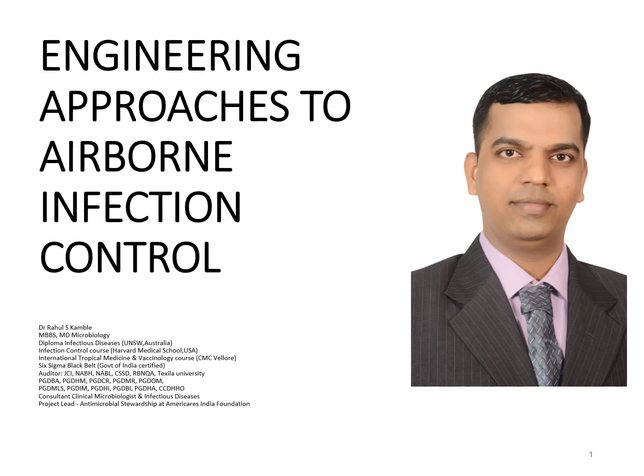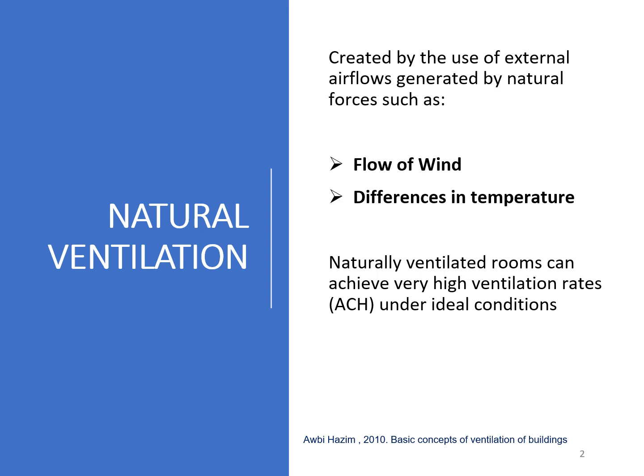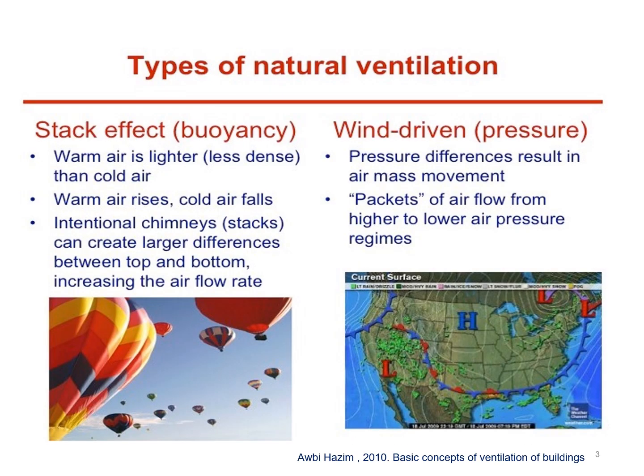Hello, let's learn about the engineering approach to airborne infection and natural ventilation. Natural ventilation is created by the use of external airflow generated by natural forces such as the flow of wind and differences in temperature. Naturally ventilated rooms can achieve very high ventilation rates under ideal conditions. The types of natural ventilation are stack effect, that is buoyancy, or wind driven, that is pressure.